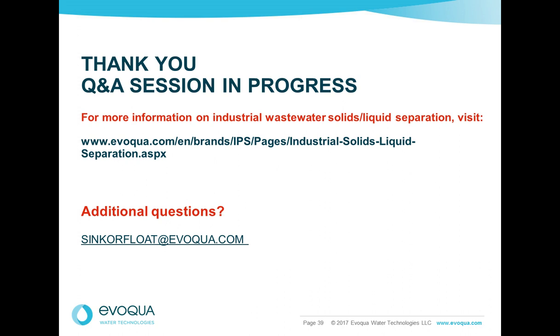We will sometimes use post clarifier or post polishing in the way of filtration, or even sometimes membrane microfiltration, in order to reduce the solids for reuse. And we have a number of applications and a lot of interest in recycling water back to the beginning of the plant, either for boiler feed water or an RO application, or service water. Recycle is also used as water. Very often it can be reused just with solids reduction, and so that's very common.